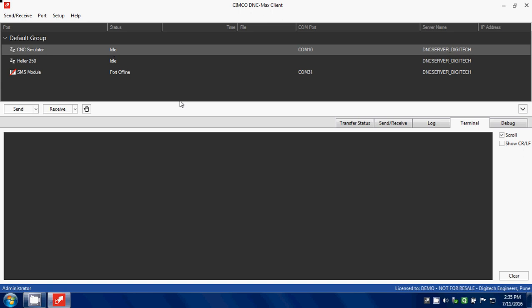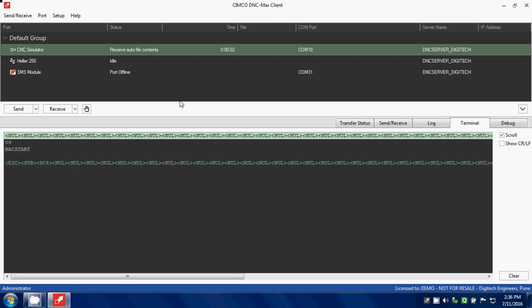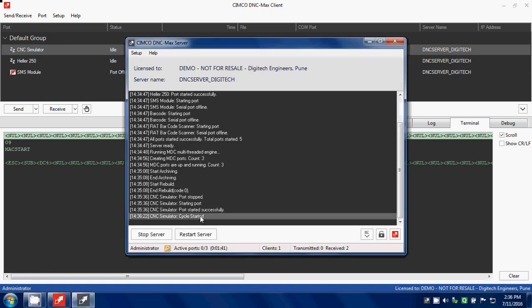In a normal situation, the operator will be calling the program on the screen, and he will start the actual auto cycle. And during this auto cycle program there is a DPRNT command. So for our testing purpose, this DPRNT command will come from HST22. So I'm just sending that command. Okay, now this has come here as MAC start. You can verify here that you get a signal called cycle start.